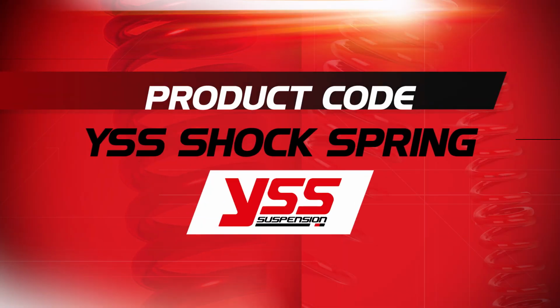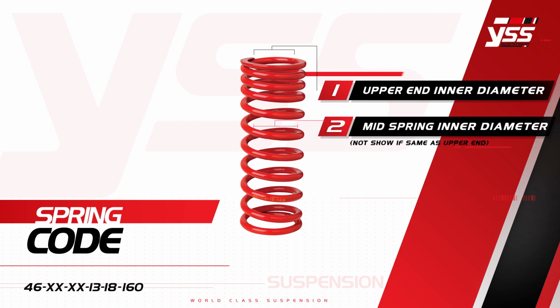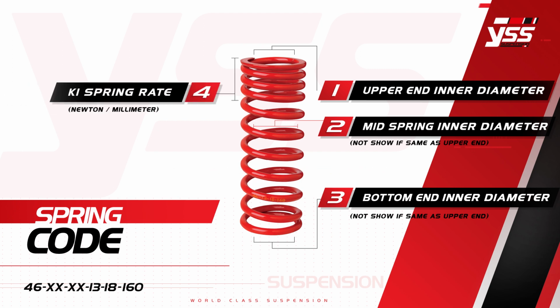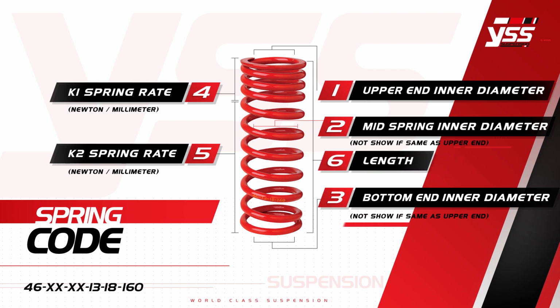YSS shock spring product code. Digit 1, inner diameter at top of spring. Digit 2, inner diameter at the middle of spring. It will not be indicated if the size is equal to the top. Digit 3, inner diameter at the bottom of spring. It will not be indicated if the size is equal to the top. Digit 4, K1 spring rate in Newton per millimeter, which is the spring hardness in the softer range. Digit 5, K2 spring rate in Newton per millimeter, is the spring hardness in the harder range. Digit 6, spring's length.